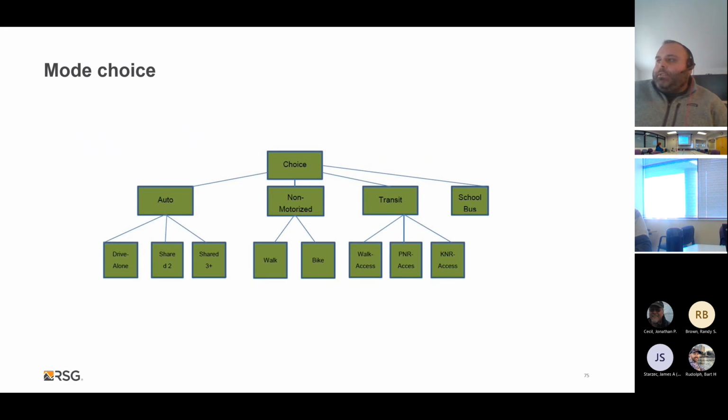The mode choice model that we use is a nested mode choice model. Essentially, the nested formula reflects unequal competition amongst modes. Similar alternatives are grouped together to reflect higher cross elasticities between them. And the nested logit model utilizes an extension of the multinomial logit model that we described previously to accomplish it.